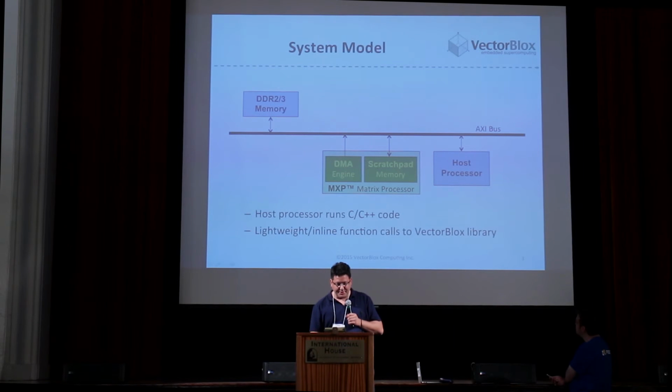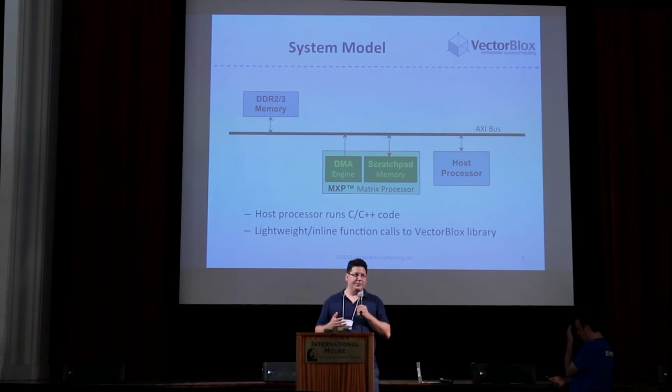It's built for FPGAs, as I said, and for Xilinx it would be built on the AXI bus, and we can use a host processor of either the ARM core for the Zynq series or a MicroBlaze. It's also fully compatible with Altera, Nios, and ARM. And what we want to do is make it compatible with RISC-V. With RISC-V, we can have the same processor system running on Altera or Xilinx or Lattice or Microsemi or Achronix maybe. So we can have a common soft processor core across all the FPGA systems. And we can also have vector acceleration through our engine.